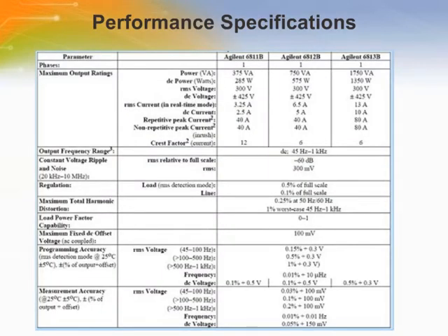This page lists the specifications of the AC source. Performance specifications are warranted over the ambient temperature range of 0 to 40 degrees C, unless otherwise noted. Specifications are for a sine wave with a resistive load at an output frequency range of 45 Hz to 1 kHz, in AC coupled mode after a 30-minute warm-up.